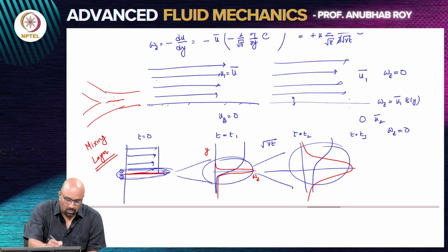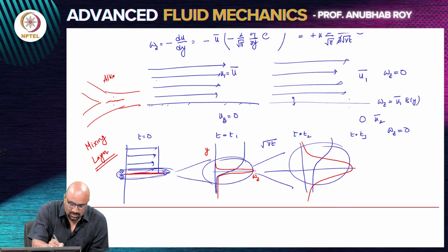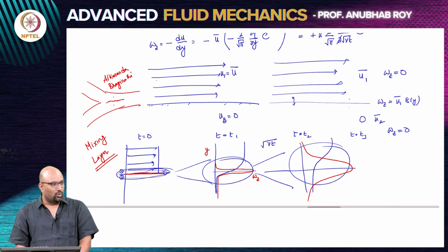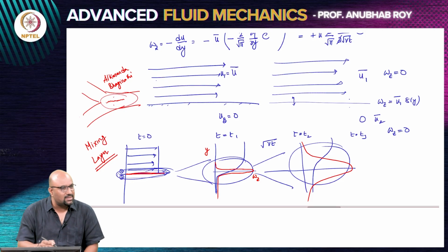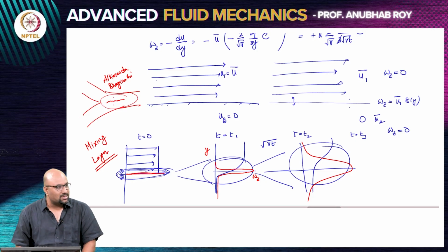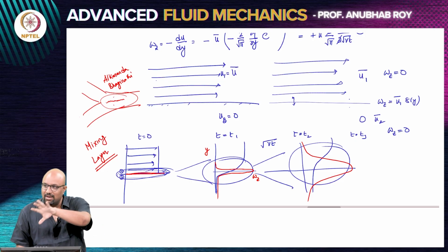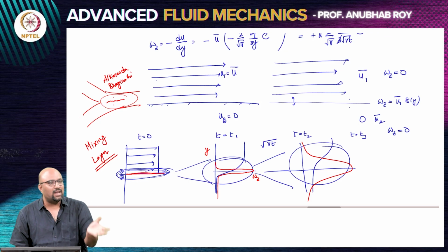When you have time, just go back and check the confluence of various rivers. In the Indian context, you have Alaknanda and Bhagirathi. If you look at the two river confluence, the picture, it is dramatic because the two rivers will visually give you a different picture. The color of the two streams are very different, and that has to do with the sediments that they are carrying and etc. So obviously that helps you visualize that there are two streams which come, and for a certain distance you will actually see that there is a distinct two streams which are flowing past, and they have different speeds. They are not moving at the same speed. You have to go a little further downstream, and the mixing has kind of homogenized the momentum as well as mass.